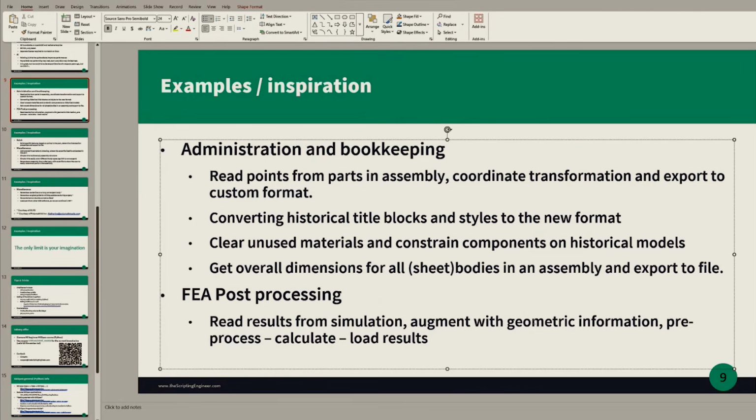I think that might also sound familiar to people in aerospace, where you need to perform buckling checks on shell structures with stringers and stiffeners. And then I performed a pre-processing and a calculation, where the calculation does the actual buckling validation check against code. That was done in the cloud on multiple instances, which automatically scale. And then the results are fed back to a file, which can then be read by Simcenter and displayed like any other results.